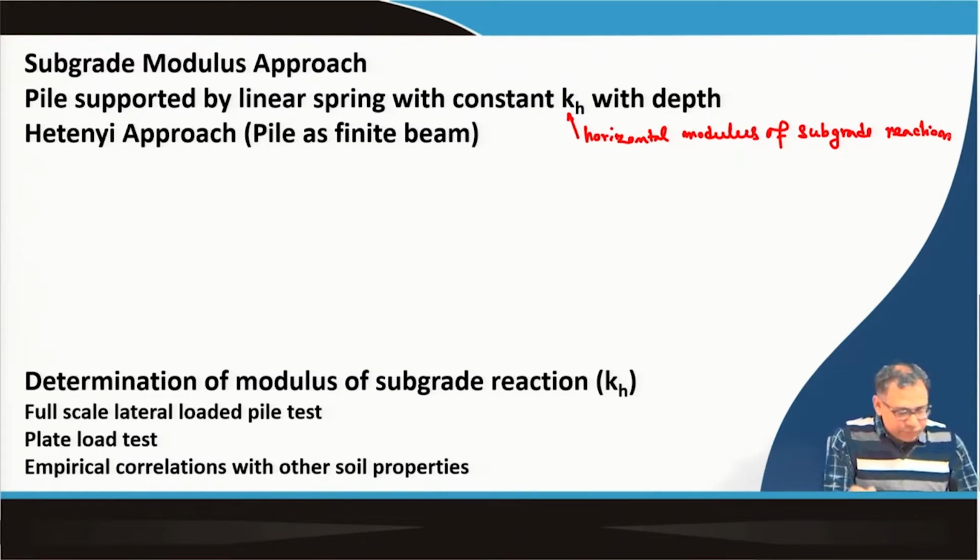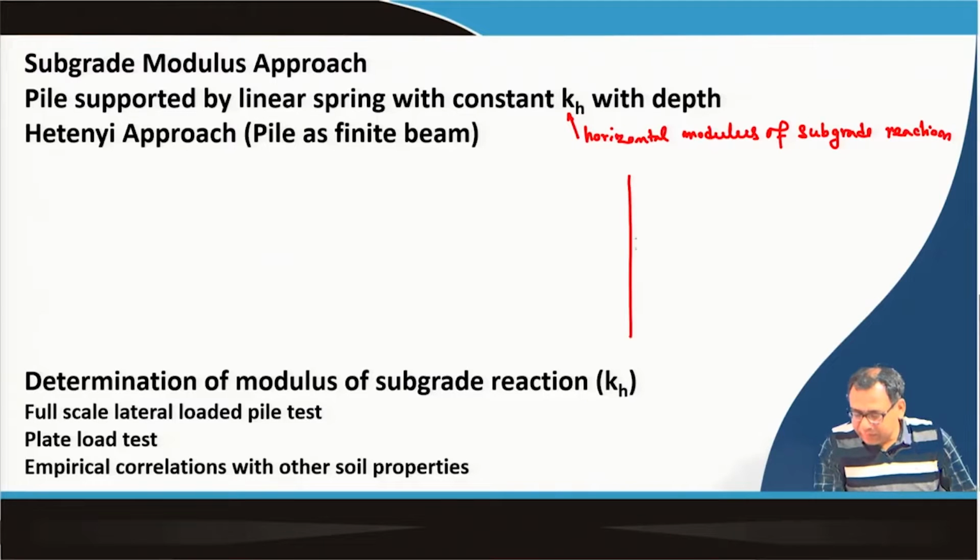So, in this approach the piles will be connected with horizontal springs, and the pile will be modeled as a beam.